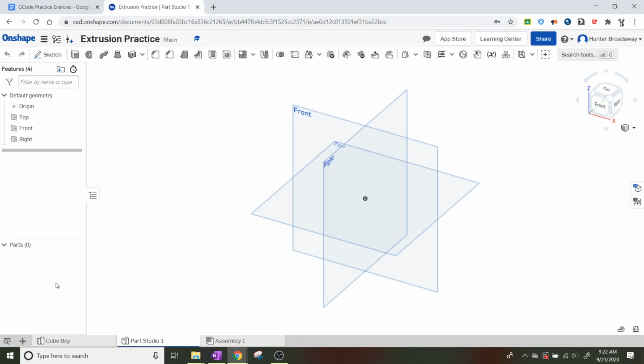Do you have this? Oh, I know what it was. Your sketch doesn't fit. There's actually a little bit of part over there on the other side that's not on the square. So you can't make an extrusion on something that's not physically there. Okay.